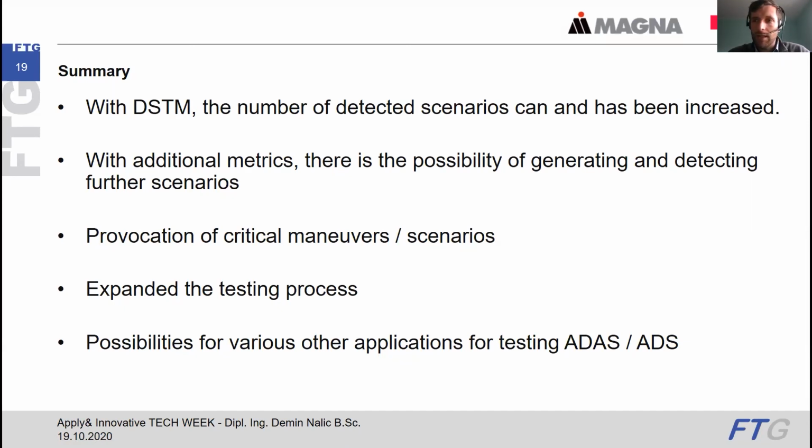The DSTM can additionally be used for other test processes which I mentioned before, for example, for testing platooning and testing column stability and maybe some other applications. Why is it possible? Because using this DLL framework, we can easily adjust the surroundings as we wish. It doesn't have to be, like in our case, just longitudinal and lateral scenarios that we took here. It can also be used for the urban environment. We can adjust pedestrians in an urban environment and manipulate them in a defined manner.